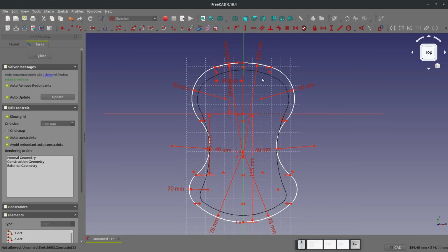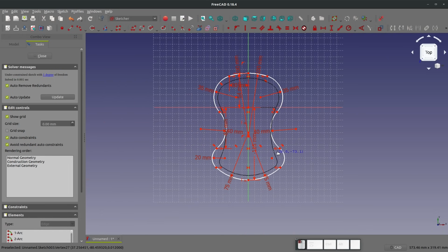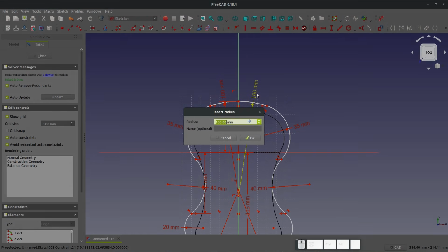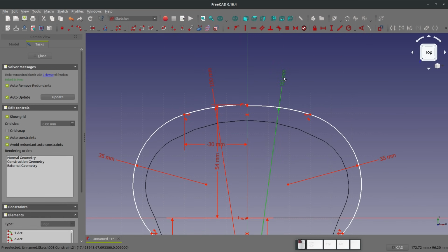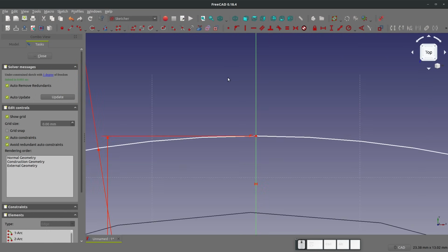Now we still have a degree of freedom, right? And that's where it gets a little bit tricky. Where's our degree of freedom? So I think what I'll do, because everything that I'm going to click and drag is probably not going to work, I'm going to change this 100 to a 90, and you can see that these points come apart. So I'll delete this dimension altogether, and let's merge these points, right?